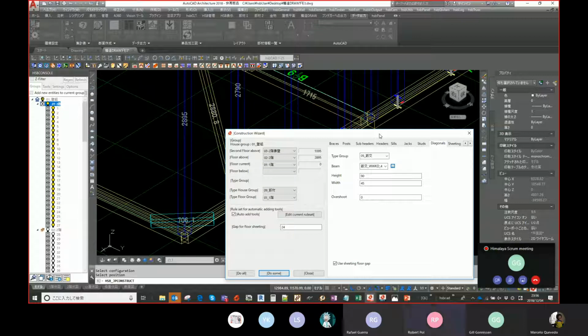Okay, so it's not all based on elements in grid. No. Item containers and grids. No, it's also based on beams. Yes, which is good. You can manually draw a floor beam, and you will still be able to position a brace on it.